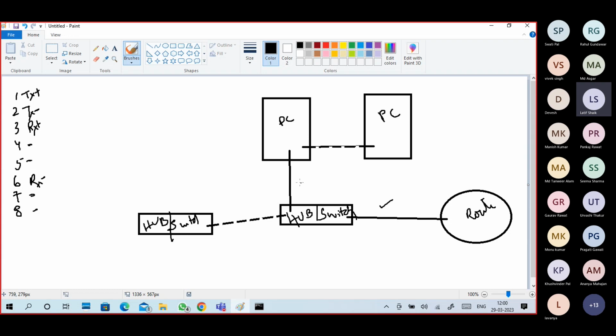If it is a straight type of cable, it means you take a cable having 8 wires, and whatever color you connect to the first pin on one end, what color you connect on this side's first pin is important. I think yeah, we use the same color.